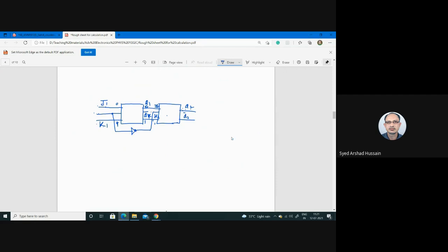Okay, so that means this flip-flop will follow or carry the output of this flip-flop just after one clock pulse. Okay, that's why this system is called master slave, and this one is slave, and this is a master, because this will follow this one. Okay, after one clock pulse. So this is a simple modification to avoid this earlier problem.